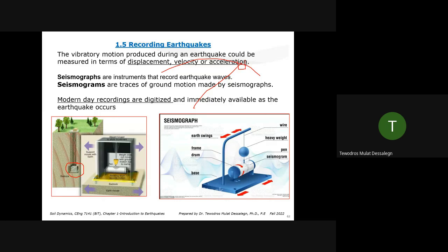Because the local soil around the surface can be affected by local conditions, we also have a recording station in the soil, but mainly we want the bedrock. From the bedrock, we can also have a recording station on the ground near the soil. But once you have a soil property, you can easily do site amplification to see how it propagates through the soil.